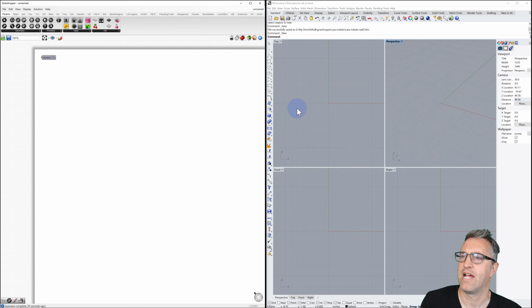The first thing that I'd like to do is to build our simple object that we're going to replicate. In this case, I'm going to do this in Rhino and build a rectangle with 3 points. I'm going to do it in the front view. I'll start at 0 and make this 8 inches wide and 8 inches high.